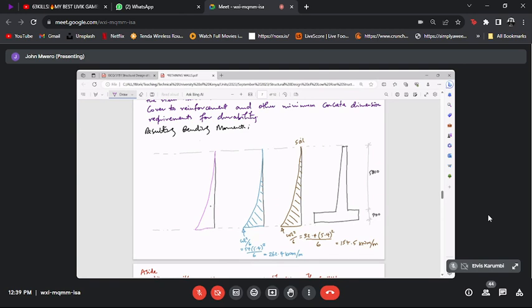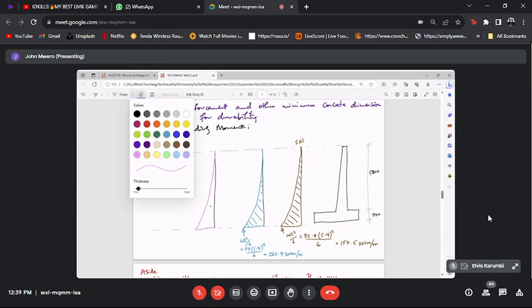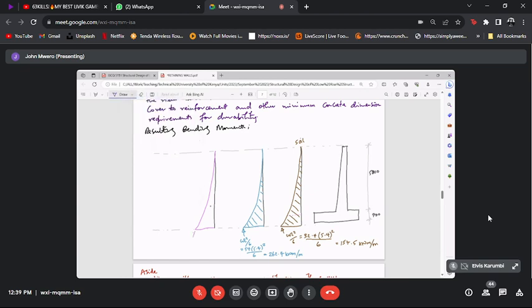You know, the wall, if it was to fail, it would fail there from our previous discussion. But we are calculating a moment that is further down here, is bigger. Ideally, the moment we should calculate for the wall is here. So we are being a bit conservative because we are calculating a slightly bigger moment than what will actually exist in the beam. Again, it would be your call as the designer to say what exactly you want to work with.